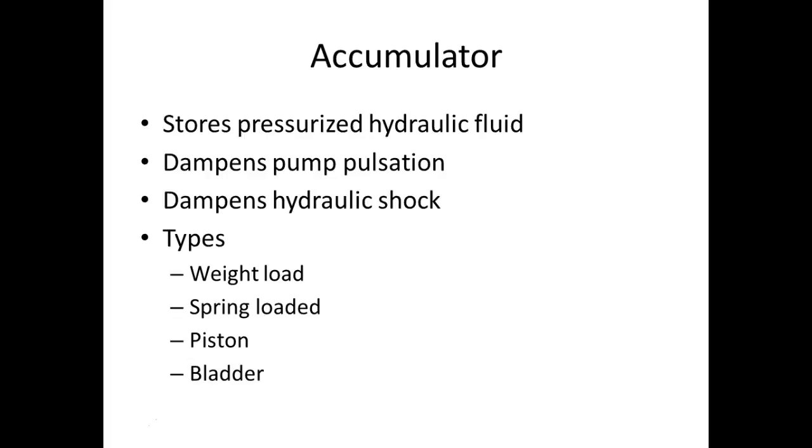So with pneumatics, we have to pressurize it before we use it. Fluid power creates pressure when you use it. So the problem is, if I've got a hydraulic system and the power fails, then I lose all my flow. As soon as I lose all my flow, I've lost all my pressure. And that could cause things to drop, things to move, things to happen, right? You know what I'm saying?